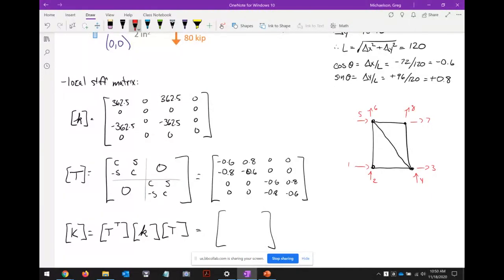And so we're talking about the diagonals, so it would be 3, 4, 5, 6, 3, 4, 5, 6. And so we would just put those terms into the assembled matrix, and we would just carry on the process. So the point I'm making is that this is the exact same process as before. There's no difference at all. It's just there's an added step, this local to global. That's it.